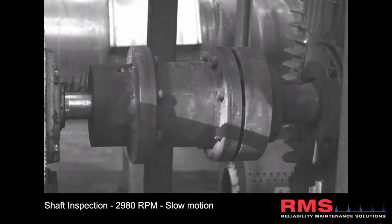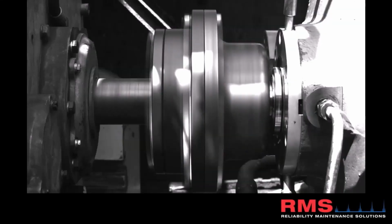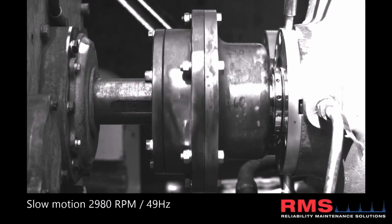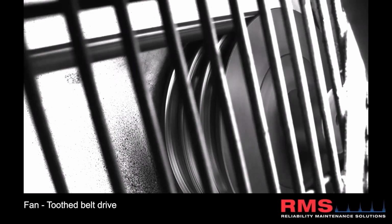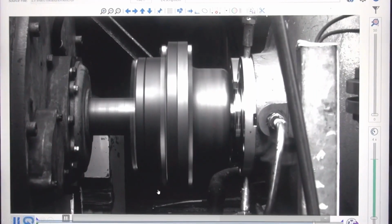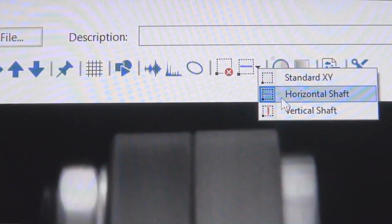Again, just going through some of these tools. There's again shaft inspection. Here's a damaged coupling. And here's that other shaft that you saw before with another look. Again, I just wanted to demonstrate that it's really the camera that's allowing us to do these new techniques with visualizing it and getting this high resolution look. Here are some belts slipping, so you can lock into the belt frequency. Here's the shaft measurement. Here's a demonstration of it. So we pick a type of shaft, a horizontal or a vertical shaft.